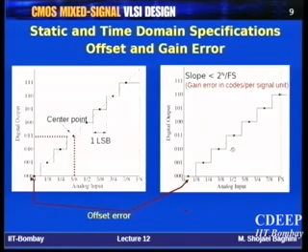For example, suppose you expect this particular 1 upon 2 to be the center point for the code 0, 1, 1. But what happens? It will now be the center point for 1, 0, 0, because your reference values have shifted. And that is because your reference values may not be perfectly correct. And there are also other reasons, like comparator resolution. So all come together and create this sort of gain error. What is called gain error is that if you approximate or plot the envelope here, ideally it would be considered a line, but practically it won't be a line.